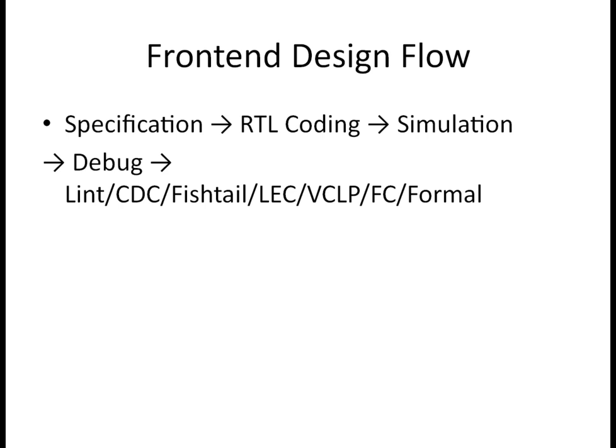Finally, it has to go to backend flows, and later it will go for fabrication, right? So in these many phases, the design which you have signed off, or the design which the designer has made, should not change. If it is changing, our intention will not be proper. The design should be correct as per the specification. So we can check this through the LEC tool